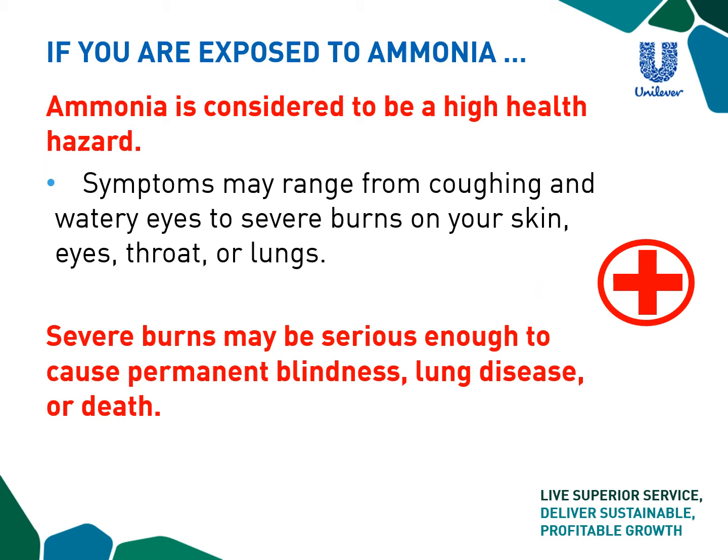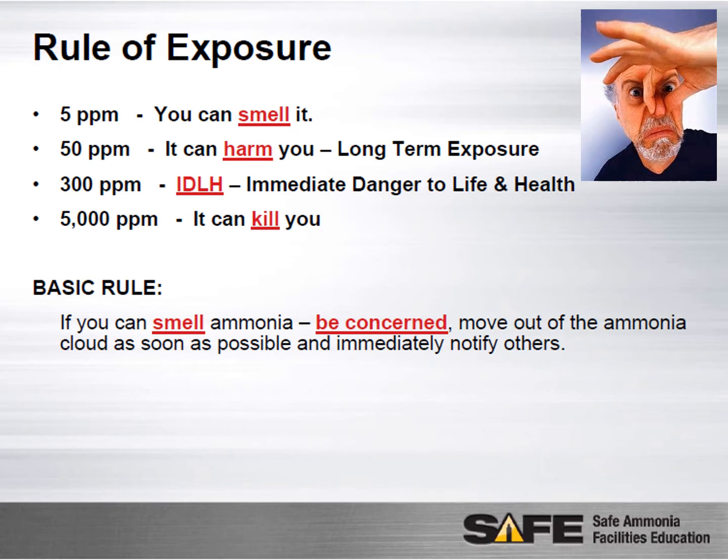If you are exposed to ammonia, it is a high health hazard. Symptoms of ammonia exposure can range from coughing, watery eyes, to severe burns on your skin, eyes, throat, or even lungs. Severe burns may be serious enough to cause permanent blindness, lung disease, or death. This slide does a good job of going over the details of exactly how different concentrations of ammonia have an effect on the human body.